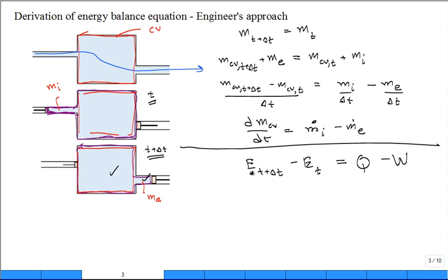So let's bust up this amount at time t. That's equal to energy in the control volume at time t plus delta t plus the energy that's fixing to exit. Expand this energy at time t. That's the energy inside the control volume at time t minus E that entered, that came in, Q. You see what we did on that? I'm trying to save some room because I want that CV term so I can divide by delta t and turn it into time rate of change of energy in the control volume. Now, the Q, I'm just going to leave its Q in.